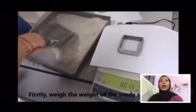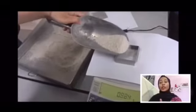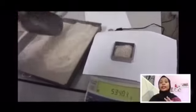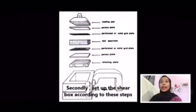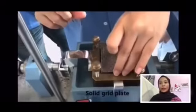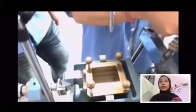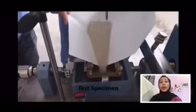Firstly, weigh the sandy soil. The first weight of soil is 1.75 kg, the second is 2.5 kg, and the third is 3.25 kg. Secondly, set up the shear box according to these steps. First, we put the retaining plate. After that, we put the perforated plate, which is a solid grip plate. Then, we put the soil specimen.